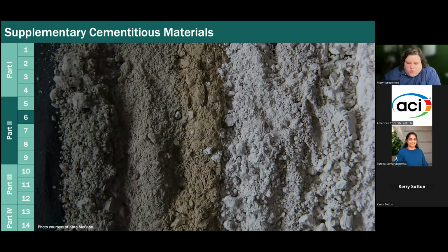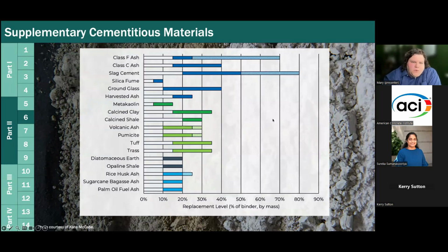Okay, one thing to note about SCMs, and here's just a picture of a bunch of them: silica fume, slag, a bunch of fly ashes. This is about as exciting as they get because they're a bunch of powders. But one thing to consider is that I think a lot of people get confused and say, oh, all SCMs are the same. You can just put however much in you want. Well, it turns out they're very different, right?